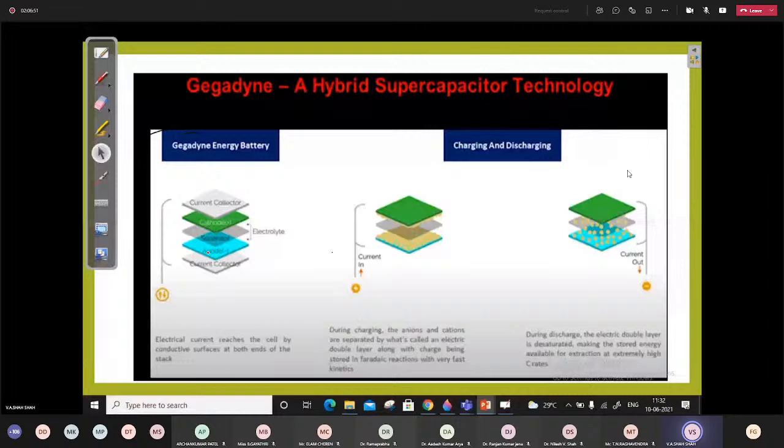And this is the energy during this whole trip, during the trip of, you can say, 500 seconds. This is how much energy it consumes, including the effect of the regenerative braking also. So now how can you size your battery and supercapacitor? From this power plot, you can find what your maximum positive power is. You can determine the average power also, and based on that we got these 2 values: this is peak power and this is average power.